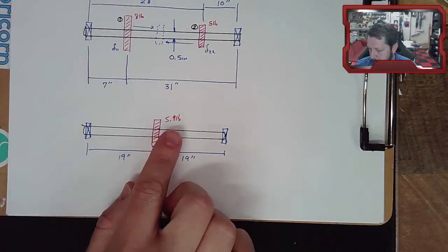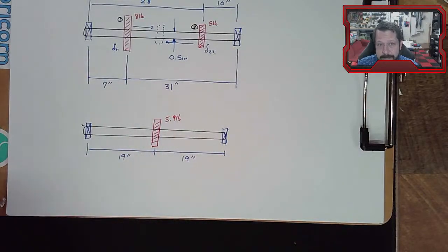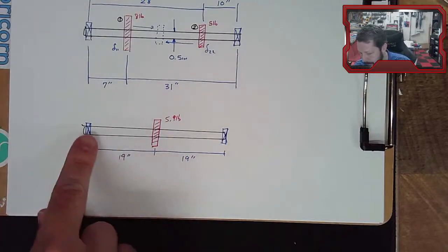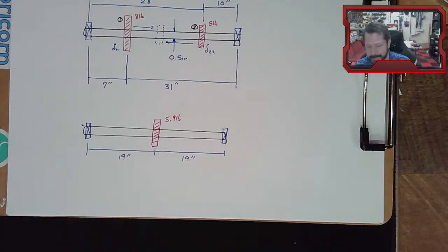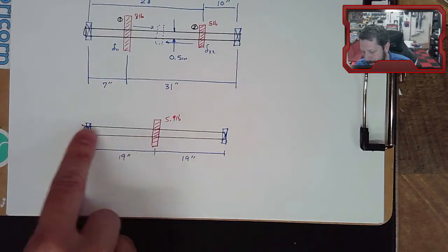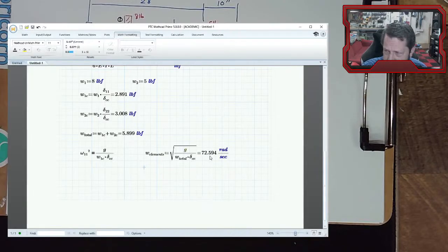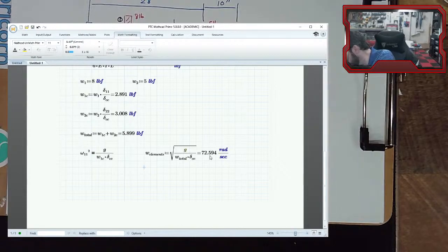If we had this same thing, just the shaft with no weight on it, it would still have a critical frequency of its own. It should just be higher than this one, but it will have its own critical frequency. So we do need to calculate the critical frequency of just the shaft. We have the critical frequency of basically this 6-pound gear on a rigid but weightless shaft right now, and we need to combine those two things together. So let's do the shaft. That is equation 722, I believe. Let me make sure. Yes, so it's right here.